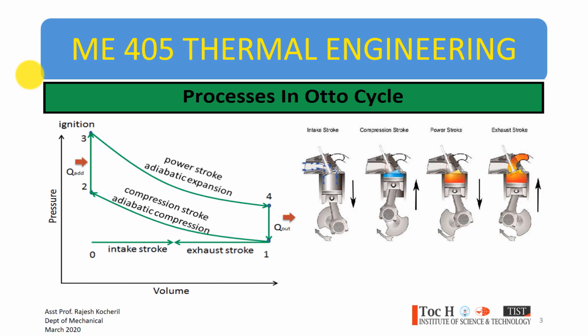Maybe you and me may not be able to stand in a traffic place where a lot of vehicles are idle and their engines are working, because the resultant noise will be so high. Therefore, in an engine it is a propagatory burning, which we call combustion. Then subsequently, when the homogeneous air and fuel mixture is burned, the chemical energy is converted into heat energy, and this heat energy does work on the piston, and subsequently it's converted into mechanical energy and onto the wheels.